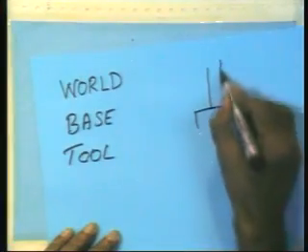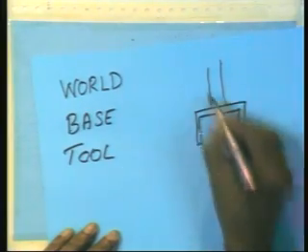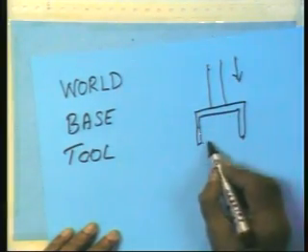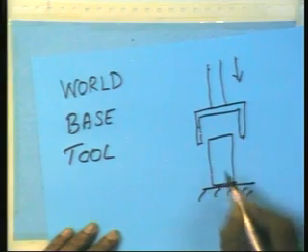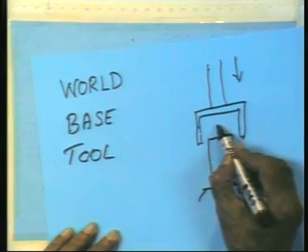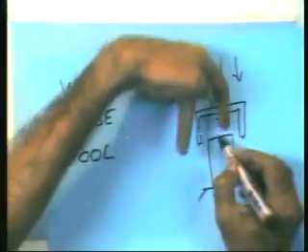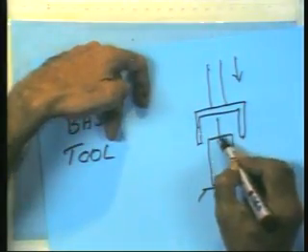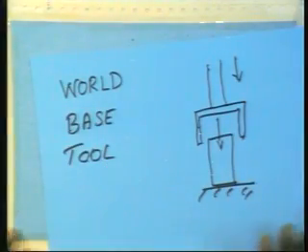The tool is particularly useful when you want an object to be gripped and the gripper has approached the object. This is the gripper, it is approaching, the object is sitting here. You have come close, then you simply tell it, move ahead. Move ahead means in the tool coordinate system, along a particular axis, keep going in that direction. Give that axis. Okay, I think with this I will close today's lecture.